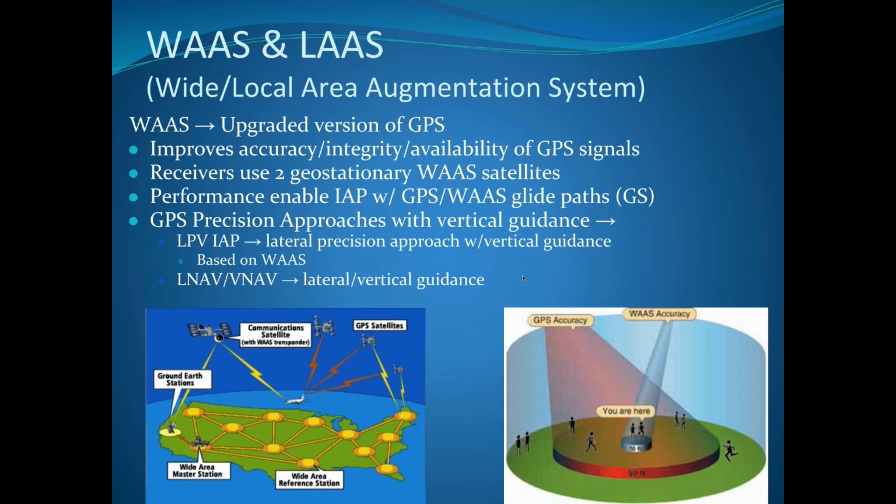Yes, it does. It's just that with the studying from the FARs, precision and non-precision, I was kind of trying to put it together a little bit. Yeah. So precision, you're going to have more accurate and lower minimums. Non-precision, you'll have higher minimums, because with a non-precision approach you're not going to have that vertical guidance as well. Does that make sense? Yes, it does. It kind of makes sense. I'm just trying to put it all together.